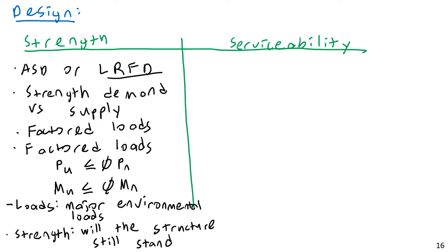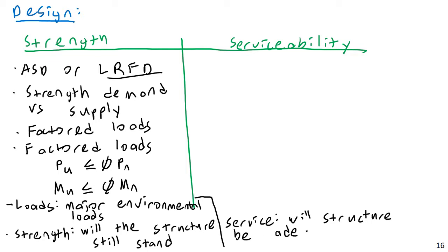Serviceability, though, is the opposite. Serviceability is not based on whether the structure will still stand. Serviceability is more based on service. What we mean by serviceability is, will the structure perform adequately under normal loading?